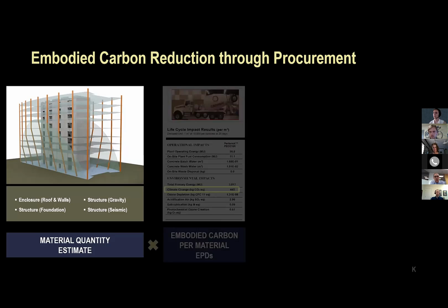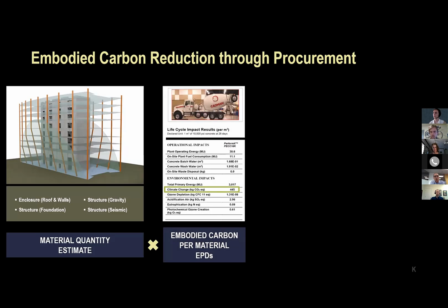Once we know our quantities, then you want to multiply those quantities times an environmental product declaration, or the information that would come from those. Industry average numbers like the NRMCA ones that Dirk was just showing exist out there in design before you know who your supplier is going to be. And certainly as the suppliers start coming on board, getting those mix-specific EPDs or the rebar-specific EPDs and using that information to then refine the quality of your data is important.